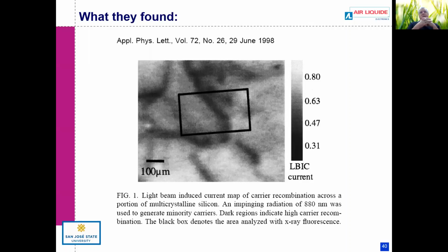So if you want to make a really efficient solar cell and you don't care how much it costs, like you're going to send it to space, then you can make multi-junction solar cells. You'll make a layer of gallium arsenide and a layer of something else and a layer of silicon, and each layer will absorb a different wavelength, create electron hole pairs, collect electron hole pairs, hopefully.